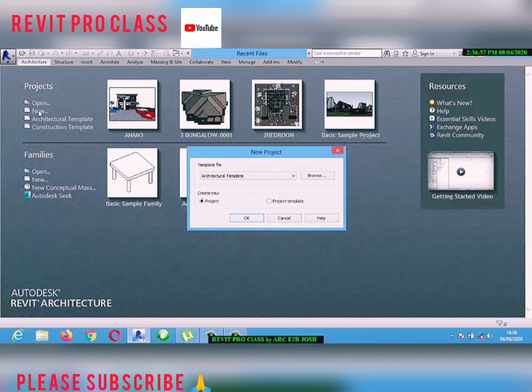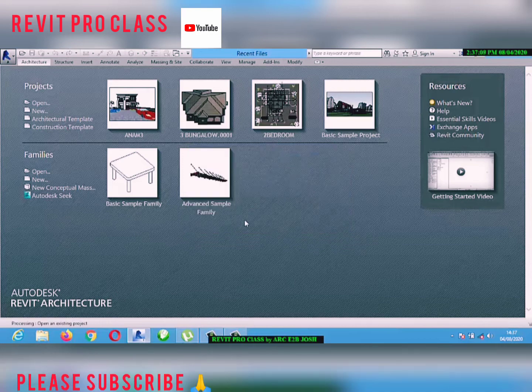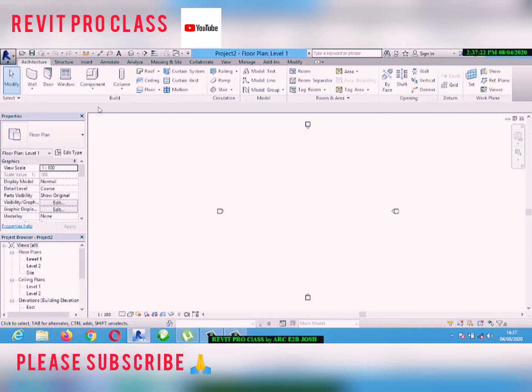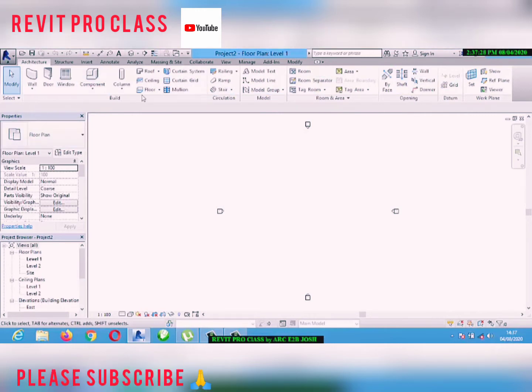Now, by the time you click the new, the first thing you're going to see is this. So this is architectural template and construction template. Always choose architectural template, then leave it at project, then you click on OK. Okay, so this is the interface of Revit, and let me just go through it. You see there are a lot of things on the interface, but I'll just go through it, and as we go further you get to know the importance of some of these things.